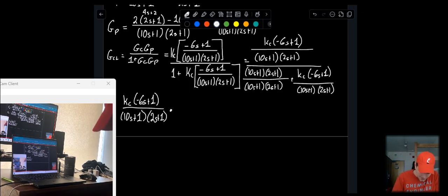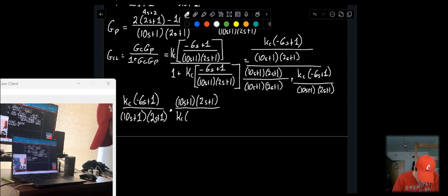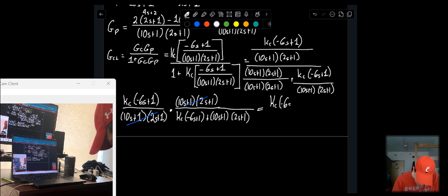So in this case, our numerator will be 10s plus 1, 2s plus 1, and then our denominator will be Kc negative 6s plus 1 plus 10s plus 1, 2s plus 1. So, of course, our forms there will cancel, and we're left with this guy right here.